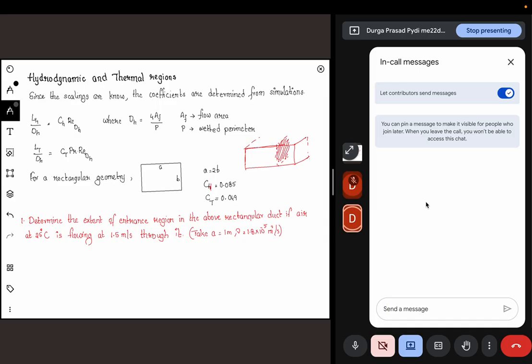So once you fix the hydraulic diameter, then you will get a constant of this. In this way, this particular constant that you are getting is fitted against different geometries. Even if it's a square, rectangle, or different cases, all of them will have the corresponding DH, and then you will get a CH correspondingly for that. This is some kind of a universal way, so you don't have to worry about which way you have taken, but convert it into this and then use that particular dimension.